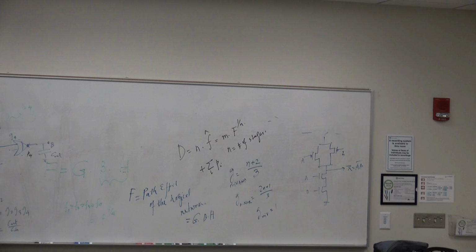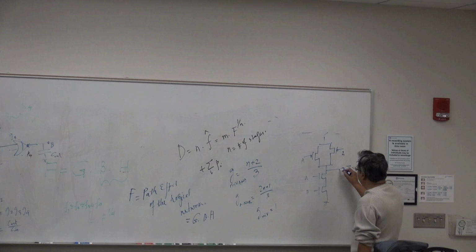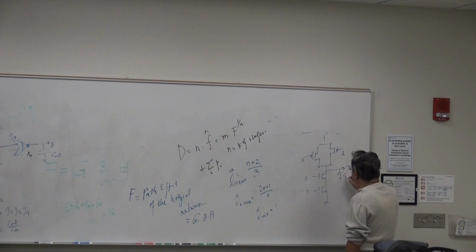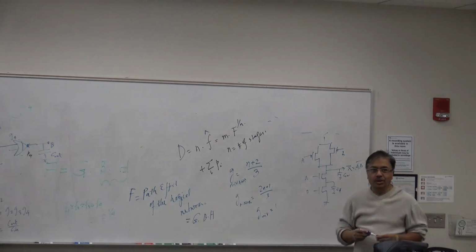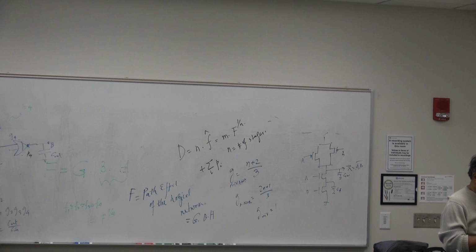No, sizing, we'll come to that. Actually, that's part of the goal of that. We'll find out the sizing. What we are missing. Is it internal nodes? Exactly. We are not taking into consideration the charge sharing between the C out over here and the internal nodes. Correct? So, there are limitations.